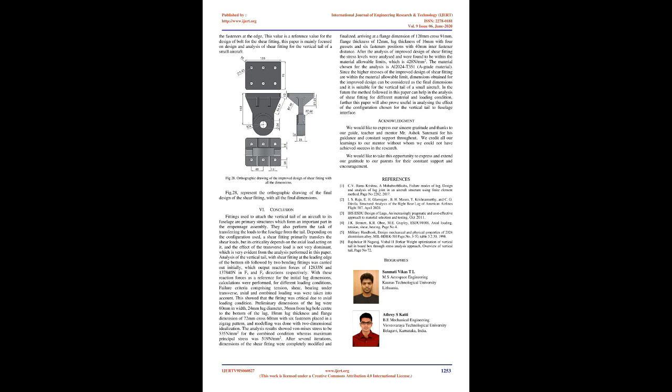The material chosen for the analysis is AL2024T351, A-grade material. Since the higher stresses of the improved design of shear fitting are within the material allowable limit, the dimensions obtained for the improved design can be considered as the final dimensions, and it is suitable for the vertical tail of a small aircraft.